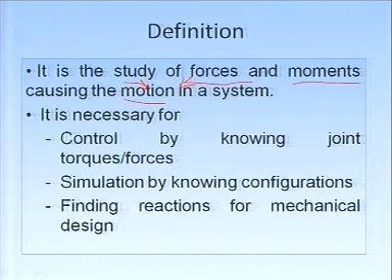So, in essence, I need to know the forces and torques to achieve a particular motion using a motor. That is for the design purpose, but for the control purpose I also need to know how much torque and force should be applied to achieve a task, so that my computer controller can send that signal to the motor drivers.